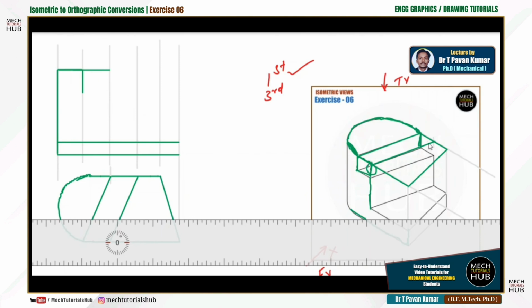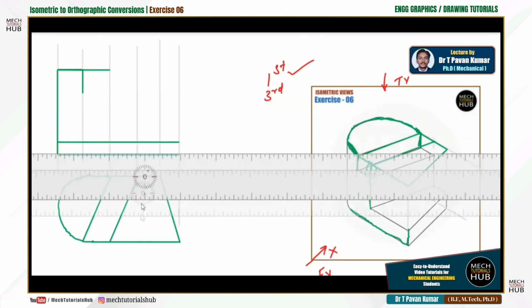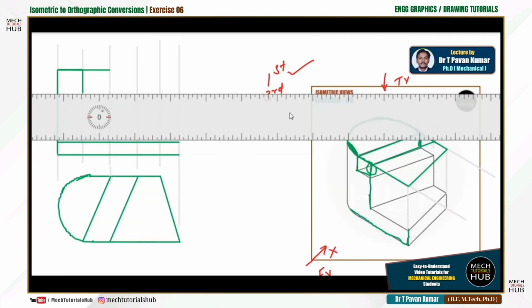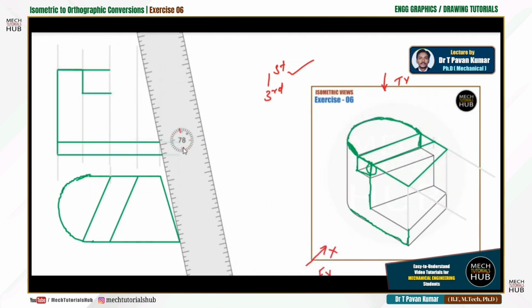After that, again as I said, these 2 lines, this vertical and the shorter vertical, I could feel from the front like aligning with each other or coinciding with each other. That is the reason I have to drop a vertical from here to the bottom. That is also fine. Then again, this horizontal we need to drop. This horizontal is important. Now remember, whatever the green lines you could see, imagine that those lines are drawn with HB pencil, need to be dark, and that is the reason those are the visible lines, what we call.